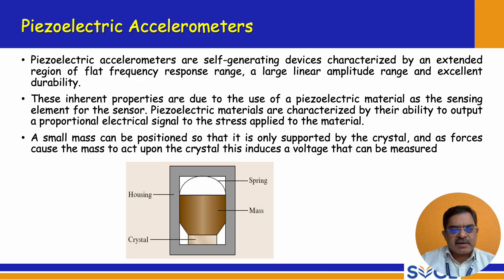Piezoelectric materials are characterized by their ability to output a proportional electrical signal to the stress applied to the material. So stress is applied, so a force is applied on the piezoelectric material and the corresponding electrical signal is generated. A small mass can be positioned so that it is only supported by the crystal, and as the forces cause the mass to act upon the crystal, this induces the voltage that can be measured. So the induced voltage can be measured, that is directly proportional to the force applied or the acceleration that it